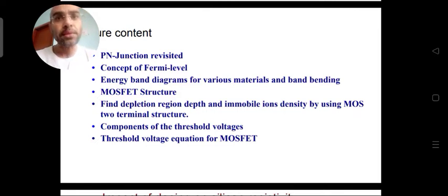This is the very first concept we should understand, because later on you will study the current flowing in the circuit and how to control that current. But unless the channel is formed, and in enhancement type MOSFETs initially there is no channel, so you have to form a conducting path between the source and the drain. Until you are able to form that, it is useless to talk about the current. So the first thing is how to form that path, or channel, under the gate region, which is not present initially. For that we have to understand the threshold voltage.